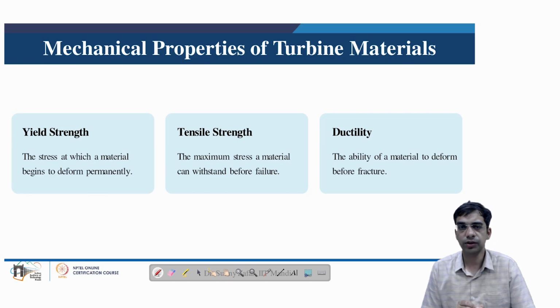which are induced should be below the yield stress, because in most engineering structures it is desired that the loading should be in the elastic zone, that is, upon removal of load the material should regain the original shape. If the load value increases such that the induced stresses exceed the yield stress, in that scenario plastic deformation will be there in the product, which will render it unsuitable for future service.